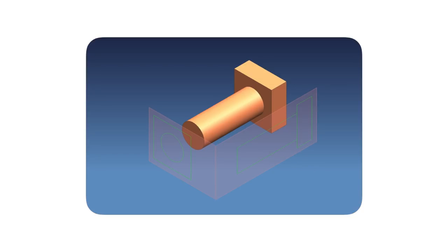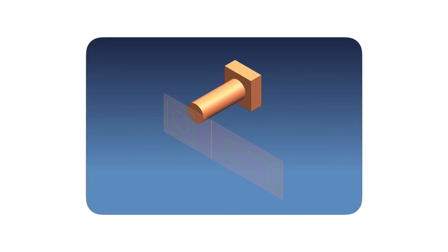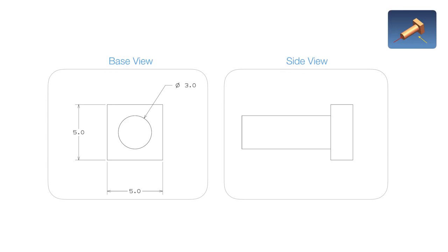That projection is looking good for dimensioning the length and the thickness, but one problem is that it's not on the same plane as the base view, so we can't draw them both on the same piece of paper. So what we do is we unwrap the new view so that it comes coplanar with the base view, and on paper it looks like this. We have our base view from before and we've added a side view, so we now have a multi-view drawing. You could also give them descriptive names like front view and right view if you want to.